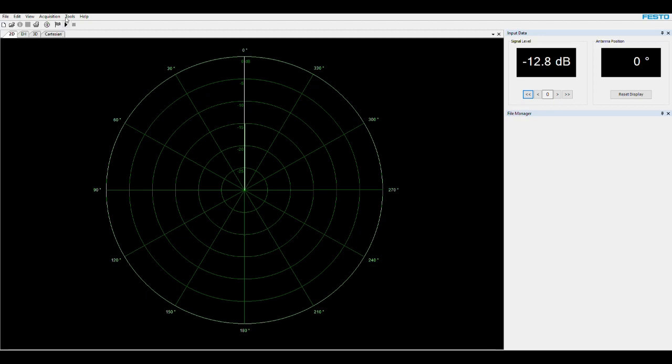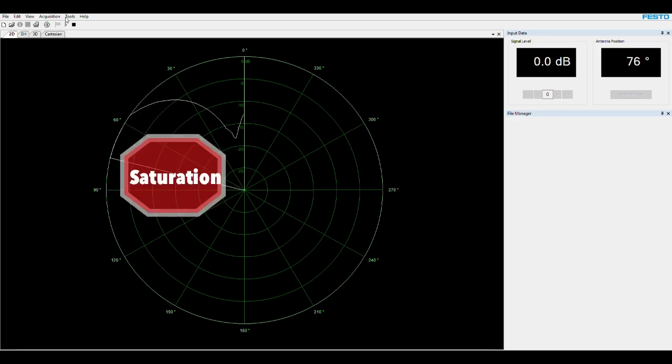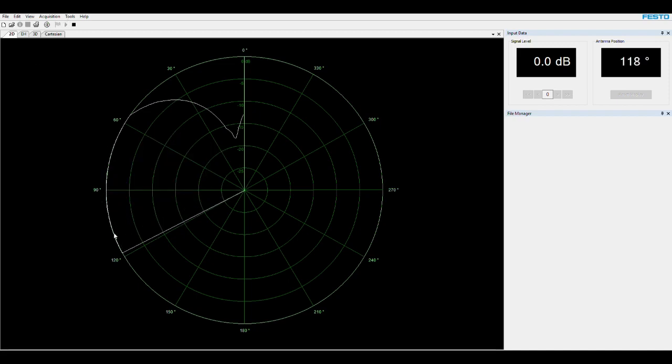So I'm just going to start with the acquisition right now. If I press start acquisition, it starts plotting the pattern for me. And because this is the E-plane, you expect to see that donut shape. Right here, you see that we have a bit of a problem. It seems the system has been saturated because we're recording the maximum value for so many angles. So we need to take care of that later on. You essentially see the shape, and again here you see that saturation effect.